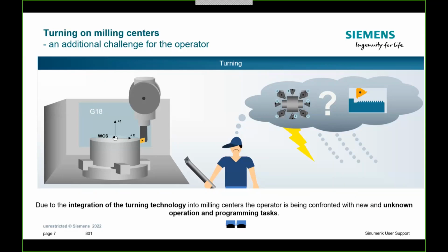Radius and diametric positioning. So how am I positioning? Is it based off of the diameter of my part, radius? All of these things I need to really pay attention to when I'm looking at these types of machines. Otherwise, I'm going to have to do everything in the post-process before it even gets to the machine. Can the machine manage these things? Actually, can the control?